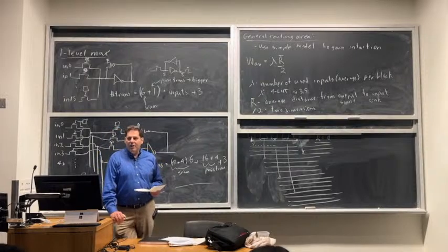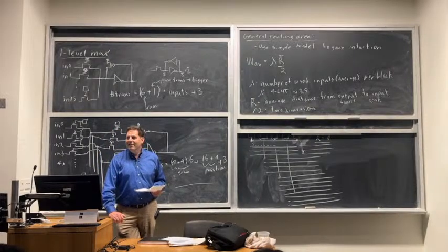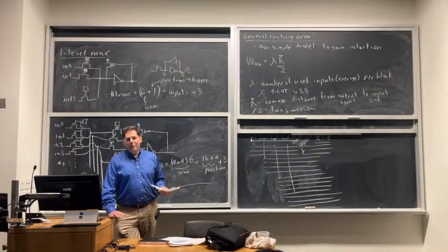What do you think the odds are of routing completion if I did that? So I built exactly 16 wires in a routing channel, and then throughout the average part of my design, I'm actually using 16 wires in a routing channel. Do you think the CAD tool will like it or not like it? So the CAD tool will never complete that, okay?